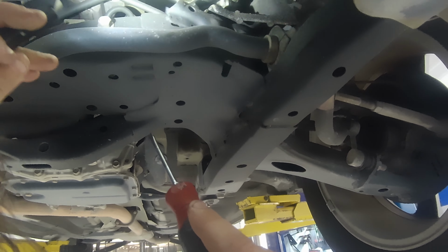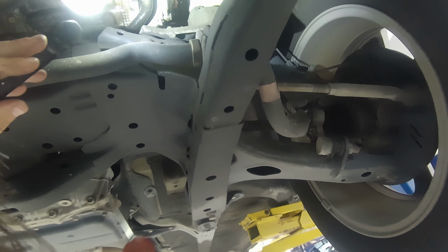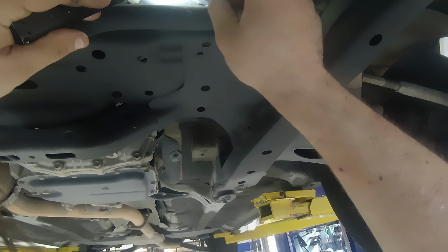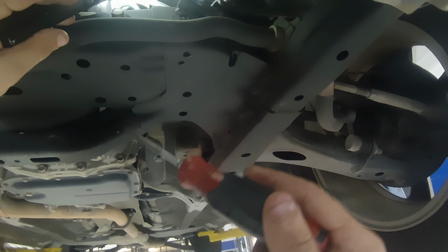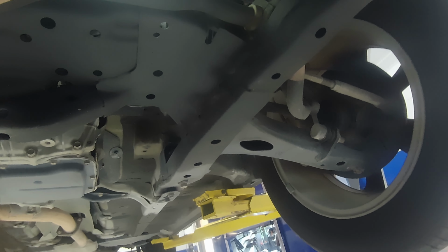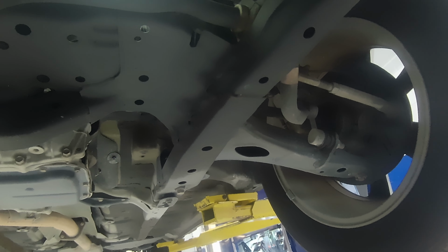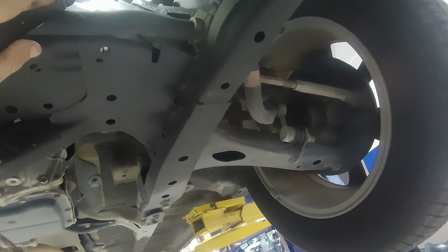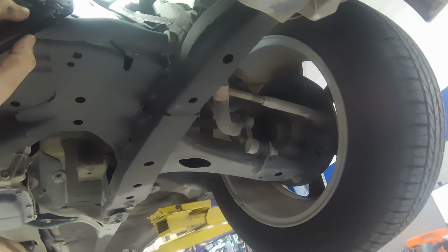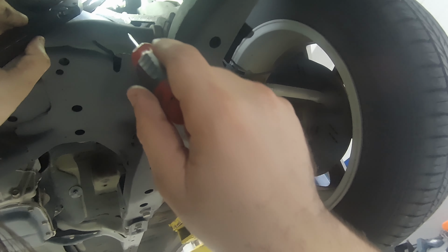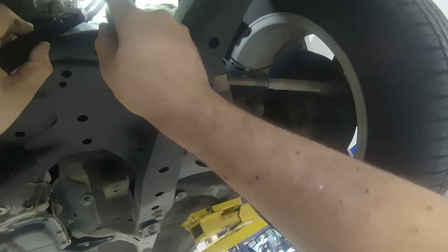You can always tell an oil leak location by looking at the cleanest spot. You see how we have all this right here, and it's nice and cluttered up right here, so someone diagnosing oil leaks would go, this has got to be it, because that's where the most is. But you have to go backwards with an oil leak. If you have an oil leak that's constantly seeping and dripping, it's actually going to be washing the area away.